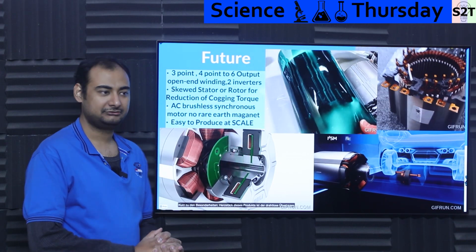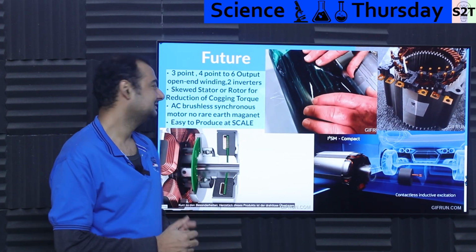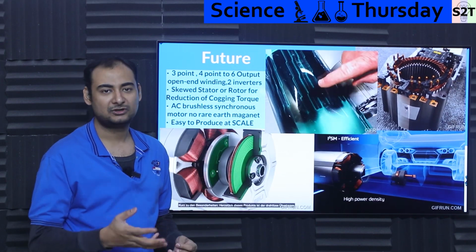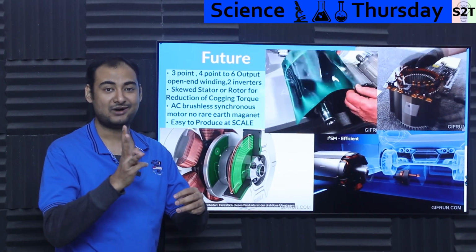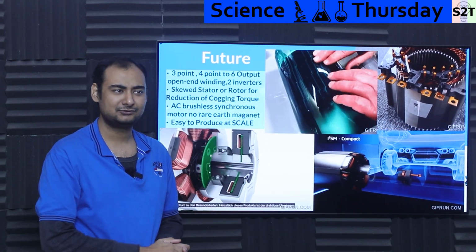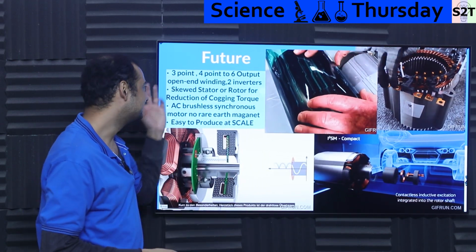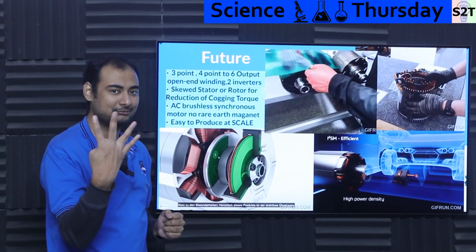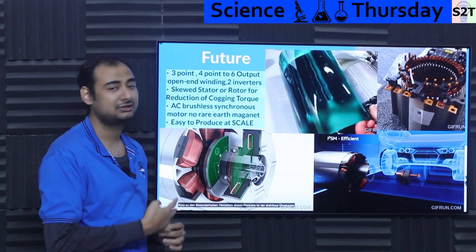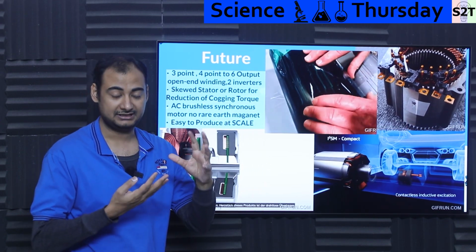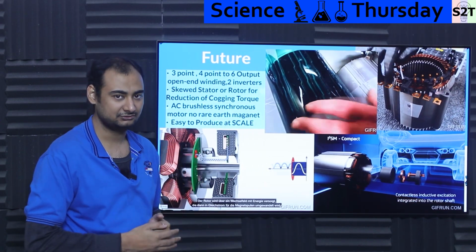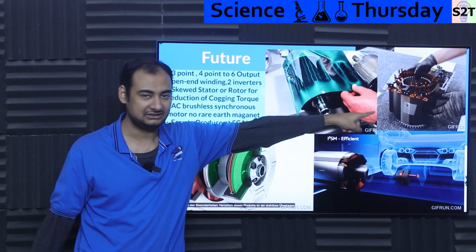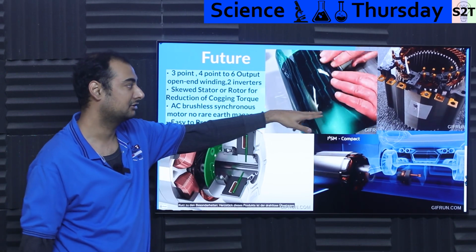Then we come to the future of this Omnisire product. So you started with the early days of 3-phase delta connection. Some were weird motors where they had 3 Y outputs and 1 neutral internally wound. I have no idea why, but they did. So we started with 3 points coming out of the motors. Then some companies have 4 points coming out, so you can do a proper Y connection or utilize the rotor stator as an inductor if you wanted to do it for charging circuits. Now companies are moving towards 6 outputs, like this puppy. It's from Kia. I have linked the teardown video down below.